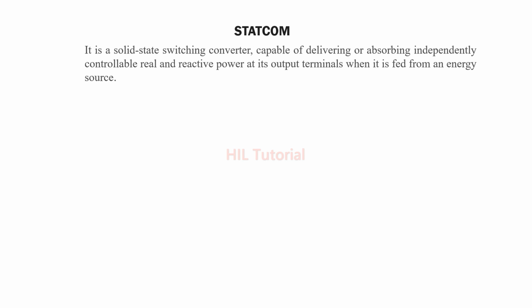Generally STATCOM is a solid state switching converter which can be useful for delivering or absorbing real as well as reactive power to the grid, while it is fed from an energy source, and this energy source could be a DC power supply, or generally it is a static capacitor.